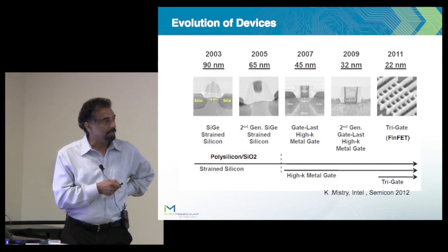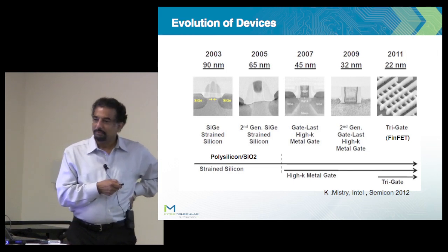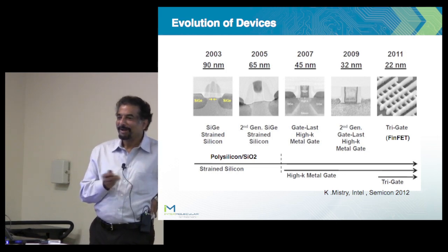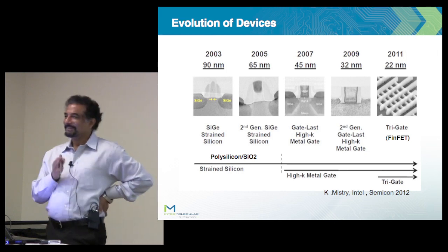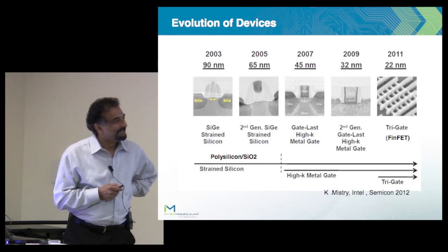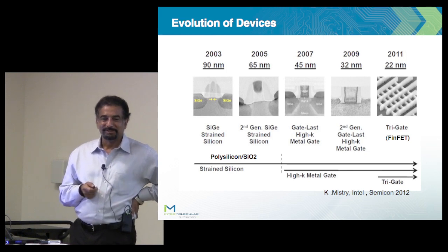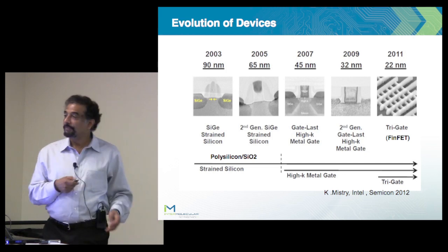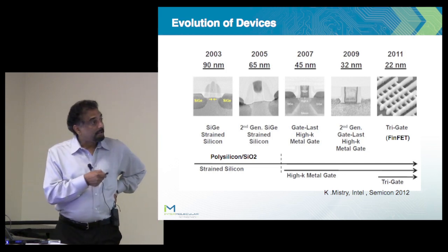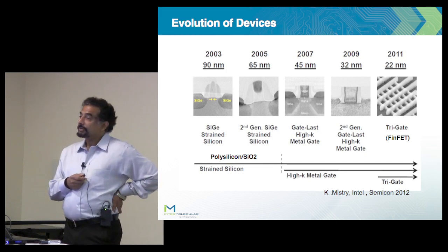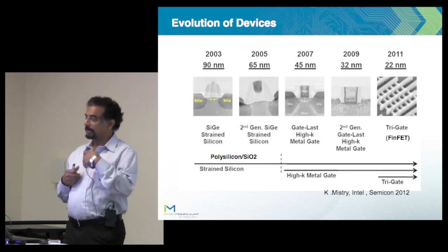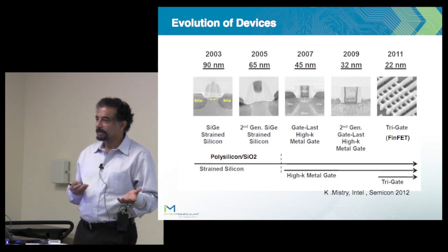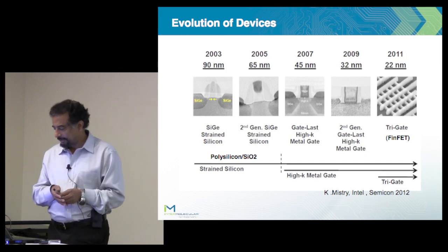This is what Intel calls a tri-gate. It was introduced initially as a FinFET by Dr. Hu, not the guy with the TARDIS, but HU, not WHO. And I believe one of Krishna's students, Sujay, is that right? Yeah. So they introduced the FinFETs, and Intel has been, like in most of the process areas, a pioneer in introducing it into large-scale production. And with that, there's come a whole set of challenges, because the high-K metal gate has also got to be integrated together with these, what we call the fins.